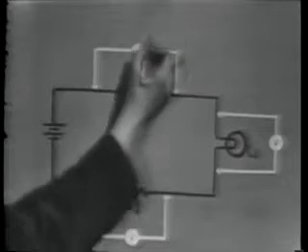By now you should be well grounded on what readings you'll get by connecting a voltmeter across an open or a shorted component. You'll have to use these indications to tell whether the component has an open or is shorted. And now let's analyze this circuit. When the voltmeter is connected across R1, it indicates 55 volts.